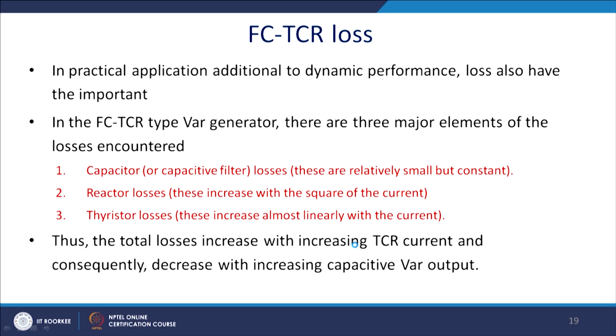Now, FC-TCR losses. Since the capacitor is connected fixed, the losses will be quite low. In practical applications, in addition to the dynamic performance, losses are also very important. In the FC-TCR type Var generation, there are three major elements of loss. The capacitive filter losses are more or less constant. Thereafter, reactor losses increase with the square of the current, and the thyristor losses,